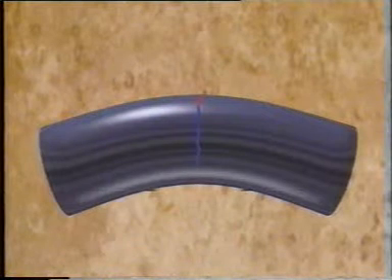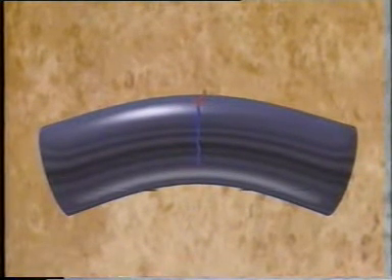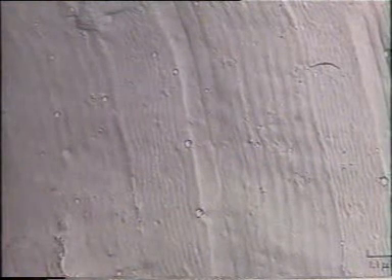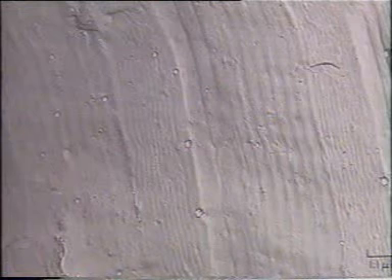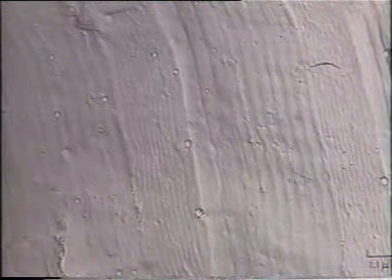gradually progresses through the metal. The crack deepens and weakens the part as it goes. In relatively ductile metals, each stress application high enough to cause a crack to grow forms a tiny ridge-like striation at the tip of the crack. These striations are frequently visible in electron microscope examination of the more ductile metals. They are actually growth marks, analogous to growth rings in trees.